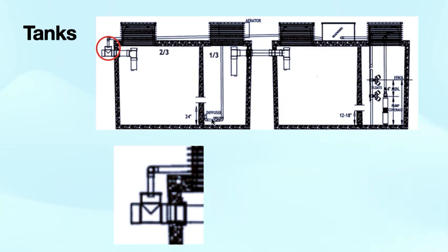One last thing about the tanks, and this will be one of the reasons why specific tanks for this system will need to be found, whether it's with a precaster or discussed with your distributor that's selling you the plastic tanks. In this first tank where the aeration is, we want this flow-through hole to be about 2 feet off the bottom of the tank. Now, if the hole is higher and you're using baffles to get down to about this 24-inch mark, that's perfectly fine. But this 24 inches off the bottom of the tank, that's where we want that water being collected as it dumps over into the second tank.